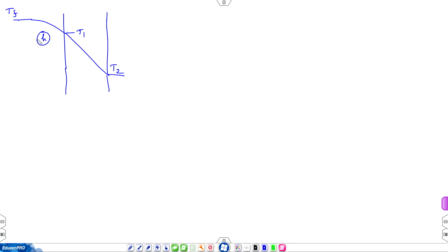So, when h is given, T1 is not known to you, it has to be found. Tf, the reference temperature, is what is given. So, you have hot gases like a furnace. If this is the slab of the insulating wall of a furnace, you have hot gases inside at some temperature Tf. The gases are in a state of motion, they are all represented by some heat transfer coefficient h. Okay.